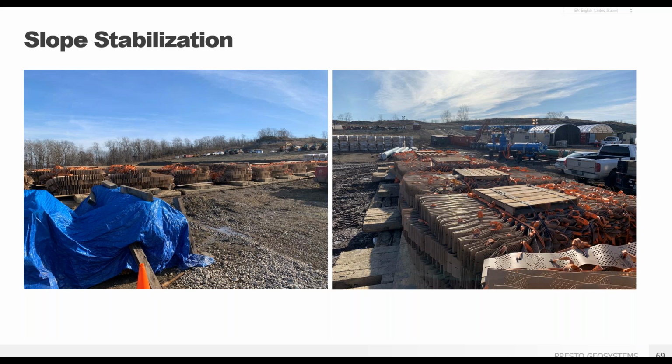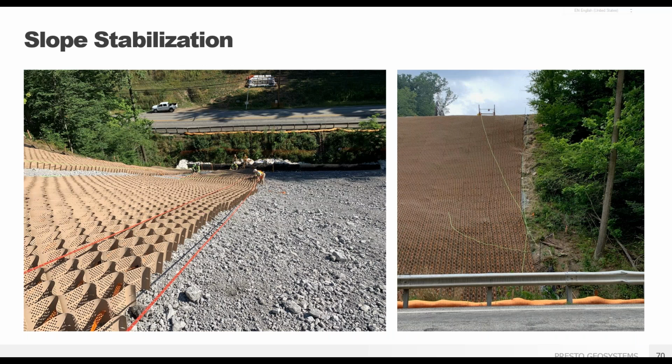An assembly line with staging tables allows that pre-building of the slope protection sections, and then the pre-assembled panels are marked for location and then taken to install, ready to hang in place on the slope. The pre-assembly means much work is done on the flats instead of on the slope side, much safer and more efficient for your workers.